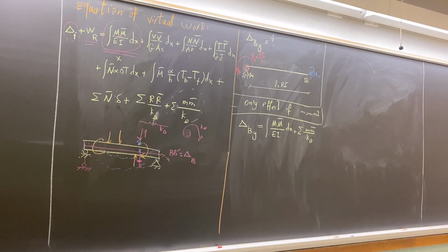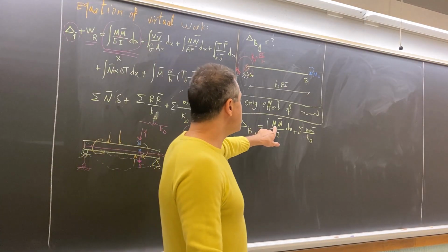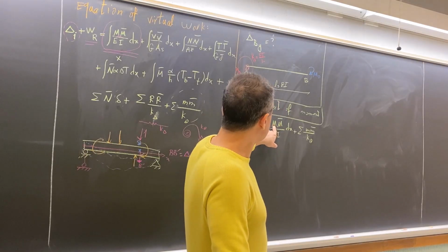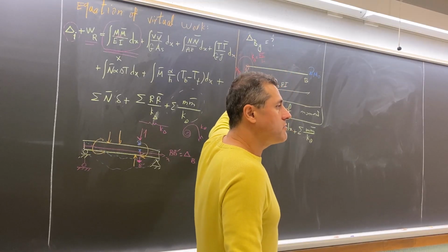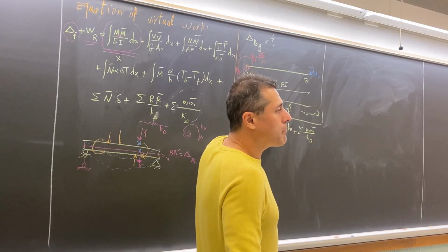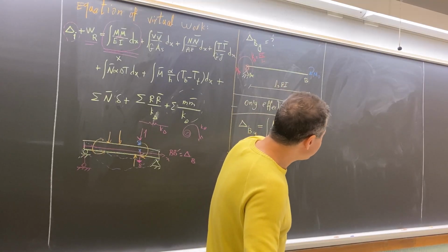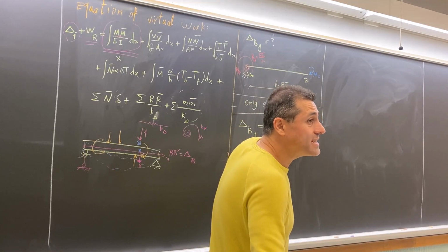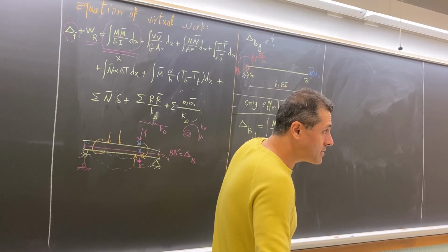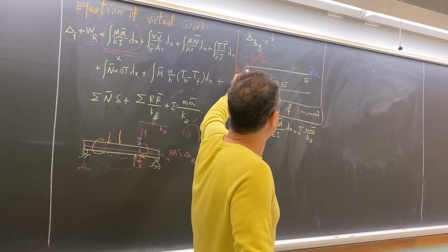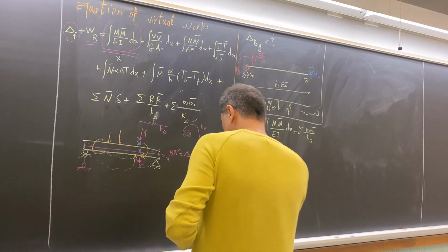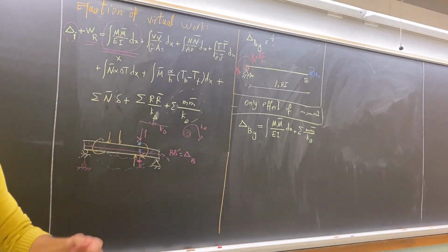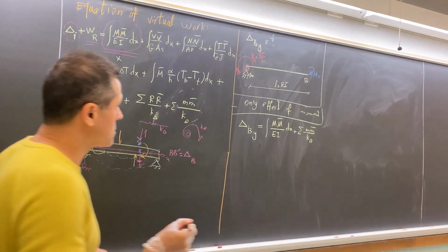Now, the first question is, what is M? M is the equation of bending moment for this beam. We go back to statics, we draw the bending moment, we derive the equation for M. This one is not the equation, it is the amount of moment inside the torsional spring under this loading. So any question for these two, which I highlighted with red?